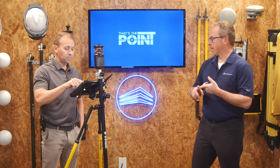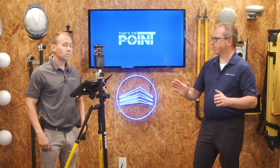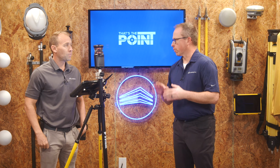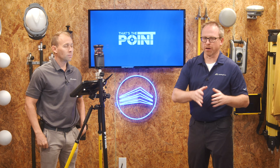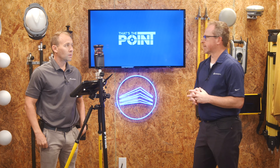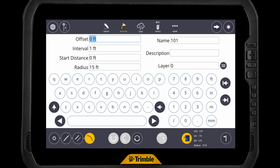And this is exactly what we covered in that previous episode with Gian about how we were able to easily create some points. This is kind of unpacking further when we're just talking about arcs, but this is going to look familiar to a lot of folks because we were able to create a bunch of interval points right there. Right. So as soon as I select the line, it popped along there. And if you look to the right, I have my edit button that I can manipulate that. So if I select that here, you see it gives me the choice of the offset. So if I was putting in a wall and I needed to account for track line as opposed to finish, I could put in my offset here for my drywall.